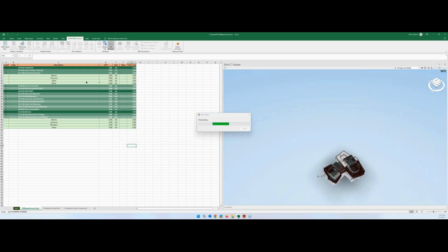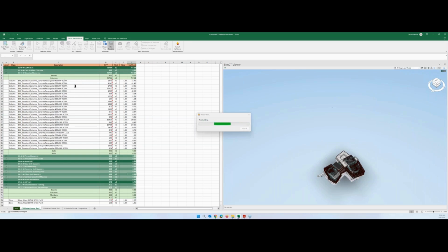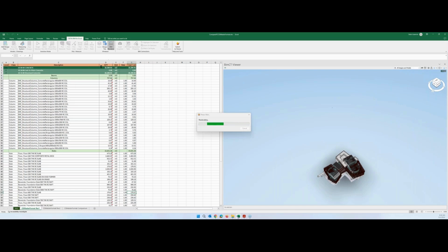all the drawing items. Now our focus here: the system will start to create all the items which are inside this 3D model. One by one they will be added. I don't have to manually select or choose anything, and the system is now calculating. Now you can see that it starts to add 2 items here. At the moment the quantity of concrete is 0, but it starts to create all the structure elements item by item, piling, walls, etc., and calculating the total quantity of the concrete.